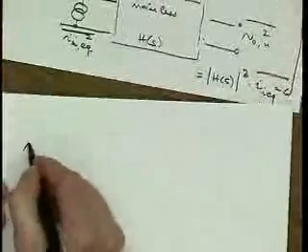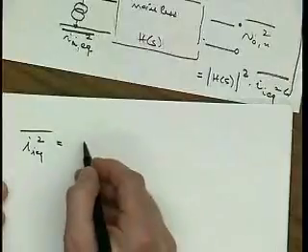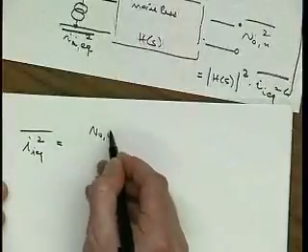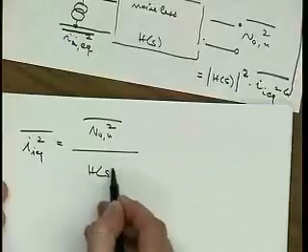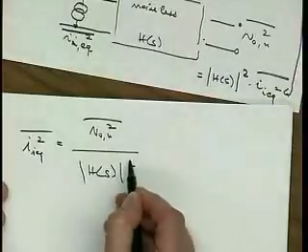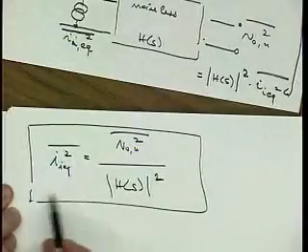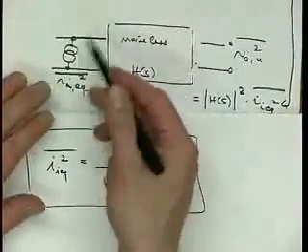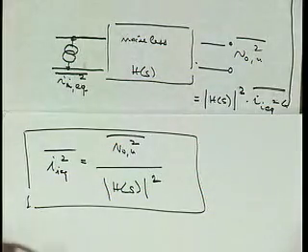So I_EQ squared is equal to V out noise, which we know how to calculate, divided by H of S squared, which of course we know how to calculate also. And you can do this also if the input is not a voltage source but a current source, so you get an analogous result.